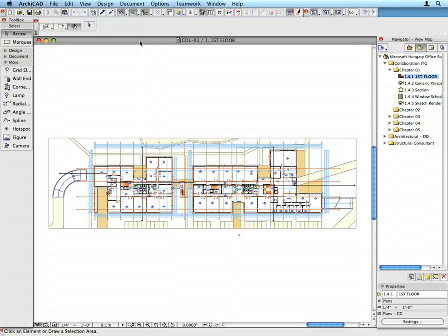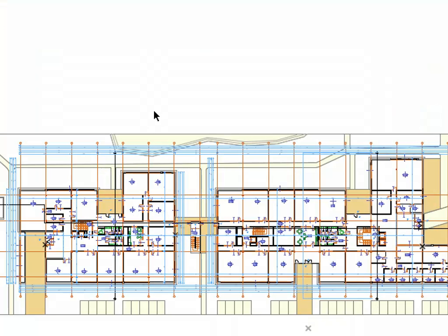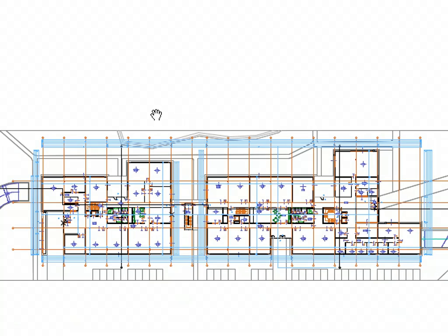Hold down the middle mouse button or scroll wheel of your mouse. At the moment you push down the middle mouse button, the cursor turned into a hand symbol, signaling that you entered the pan mode. When moving the mouse in pan mode, you can drag the view around in the window. Perform panning a few times to familiarize yourself with it.